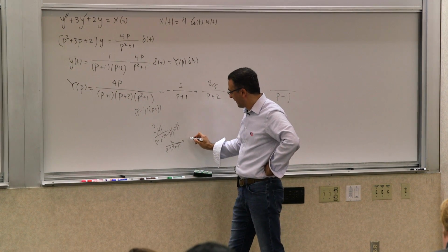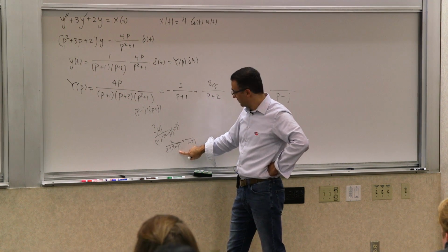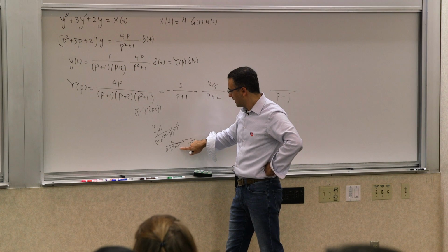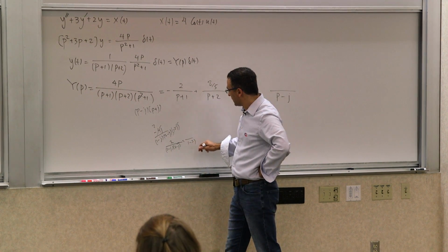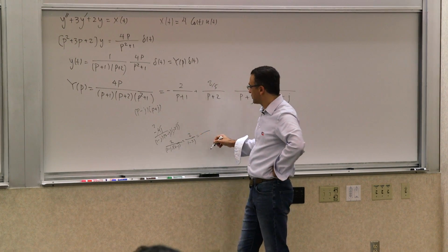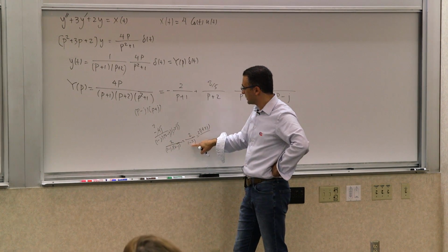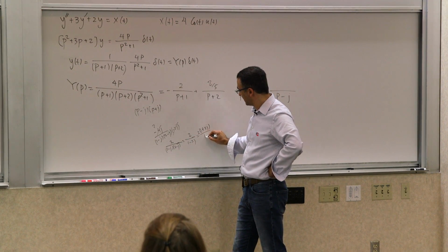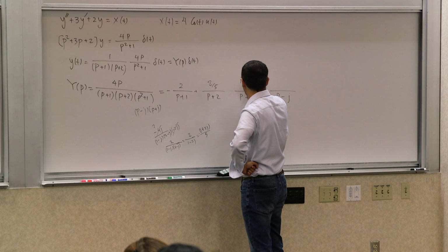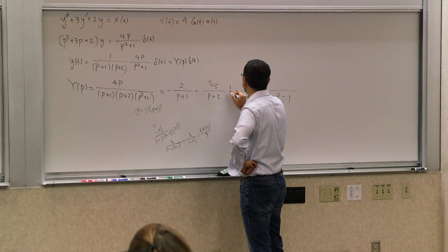Say again? 1 minus 3j, because you get 2 here, you get a negative 1 there, so you get 1, and then you get 1j from negative 2j here, negative 1j here, negative 3j. We have already taken care of that one. And then in the numerator you get 2, right? You could try to convert this into something that has the complex in the numerator. So you multiply by the complex conjugate of itself. So you get 1 plus 3j. You got the 2 up front. And then what is this? It's 1 squared plus 3 squared. It's 10, right? So it's 1/5 of that. So this becomes 1 plus 3j over 5. Or you can put the 1/5 up front if you want. 1 plus 3j, 1/5 of that.